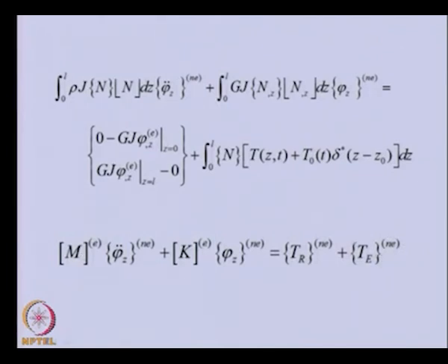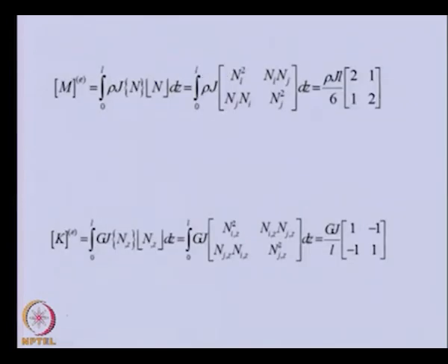These mass matrices, in the previous lecture we explained how we can obtain using the shape functions. Because this is a column vector and this is a row vector, if we multiply them, we will get the multiplication of these two vectors as a matrix. For a representative case, let us say we want the M12 element of the elemental matrix.